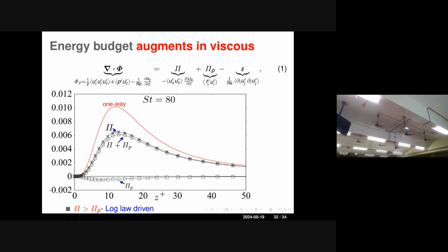So usually at the logarithmic layers, this entire transport term comes because of the production, the forcing term, with the dissipation term. Usually the high logarithmic layers are the layers where the high-speed, low-speed streaks develop and start moving. And those really get modulated by these particles. And that's the thing we started with.